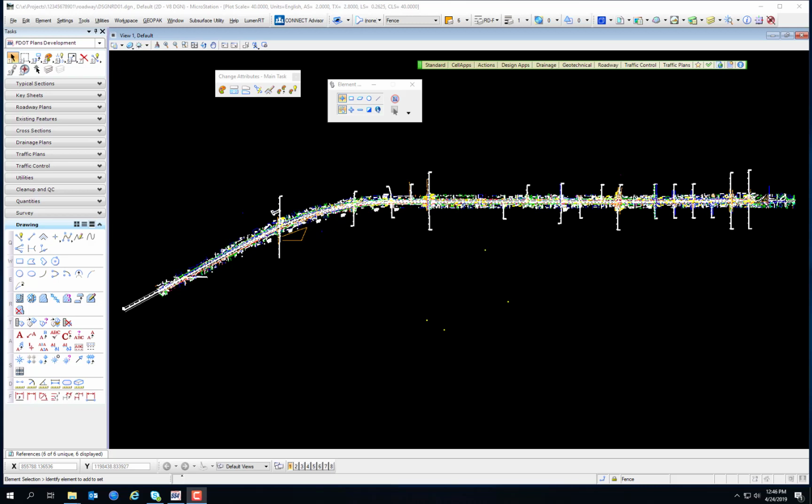Each open toolbox is either floating in its own window or docked to the edge of an application window. The arrangement of tools in a floating toolbox can be changed by resizing its window. Tools are represented in toolboxes by icons. For simplicity, the term tool is used to refer both to a tool and its icon. Within MicroStation, one tool or another is selected or active at all times. The default selected tool is the Element Selection tool, which is used to select elements for manipulation or modification. When a design file is opened in MicroStation, the Element Selection tool is automatically selected or active.